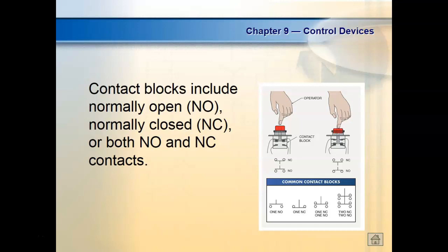Don't pay attention to the legend plate. All you're doing is looking for normally closed or normally open push buttons, right? So with that right there, you can do a 3-input NOR or NAND circuit, or use one of them as a NOT, or you could do two ANDs with that one station, because two of the push buttons are single pole double throw, which means in one position it's going to be closed, and in the other position it'll be open.